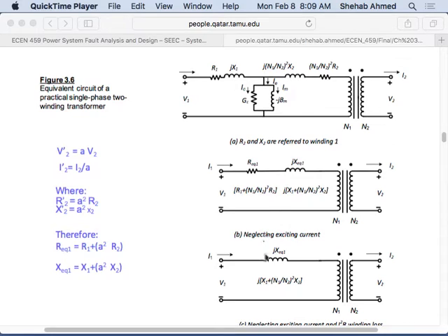Again, if your transformer is designed properly, right, you're not going to design it with a huge power loss. You will make sure that you've selected your conductors such that the resistance of these conductors is as small as possible, especially these large power transformers. Again, if you're processing 100 megavolt amperes, right, even 1% of loss is big, right? So it's 100 megavolt amperes, 1% is 1 megavolt ampere, right? So it's almost 1 megawatt of loss if you assume unity power factor. Right, so what will that do to the temperature of the transformer? It will raise it like crazy, right? So you cannot live with such losses.